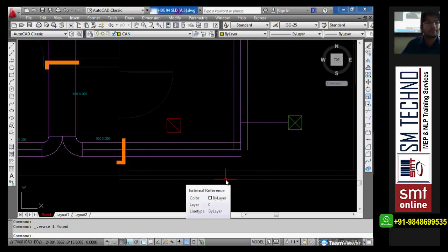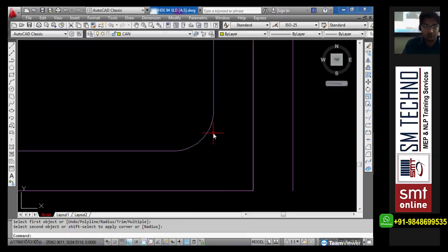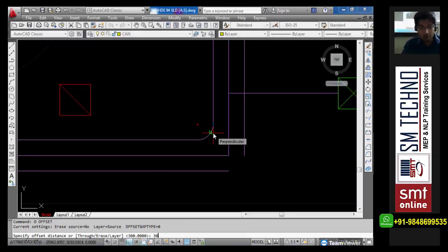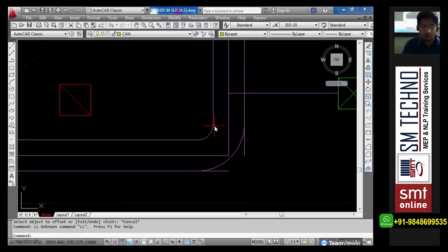Which elbow can I apply? Long run, right? So that would be 300 by 2. The fillet would be again 150 for that. 150. This end matches with this end. Total offset for 300. Use the line.